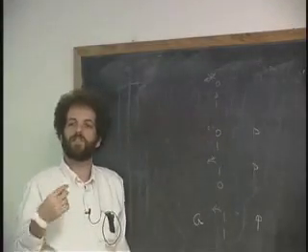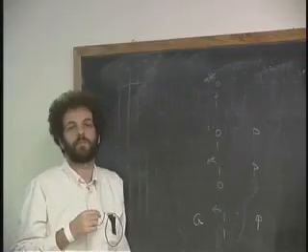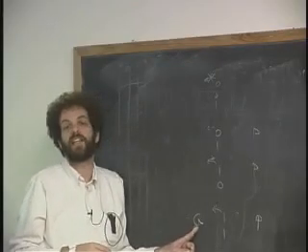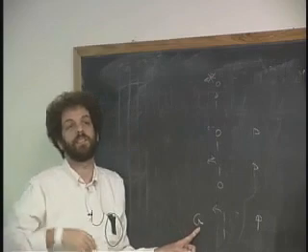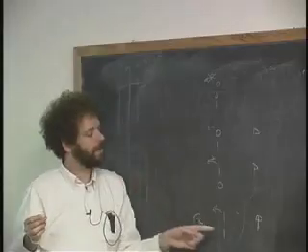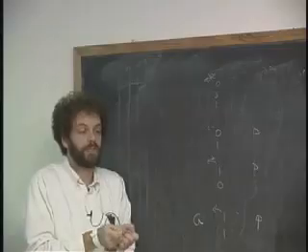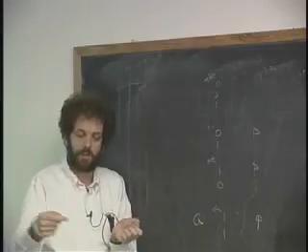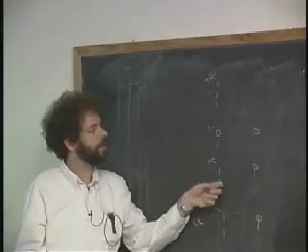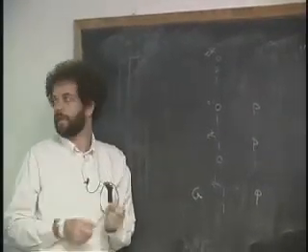Now this decision, do I generate or do I propagate, is a decision that can be made beforehand, before the carry comes in. And first of all, the generate, you can even take action on before the propagate comes in, because it doesn't matter what the carry in is, in this case, you just generate the carry. And in the propagate case, you can get all the work done and all set up, so you're just waiting for this last bit to come in, which is a slow bit that's going down the chain, saying, okay, if I have two 1s, or if I have a 1 and a 0 here, I get all set up waiting for the propagate to happen.